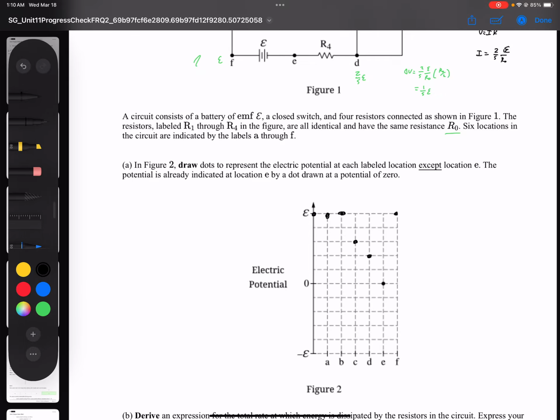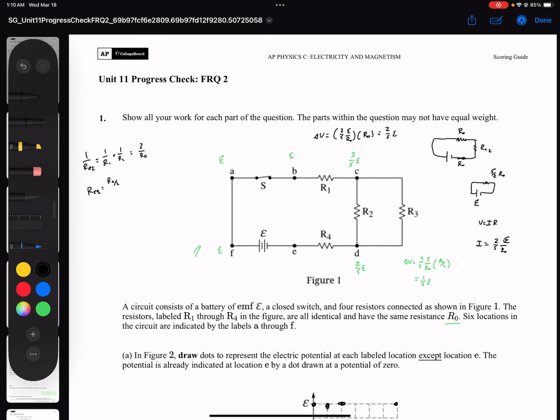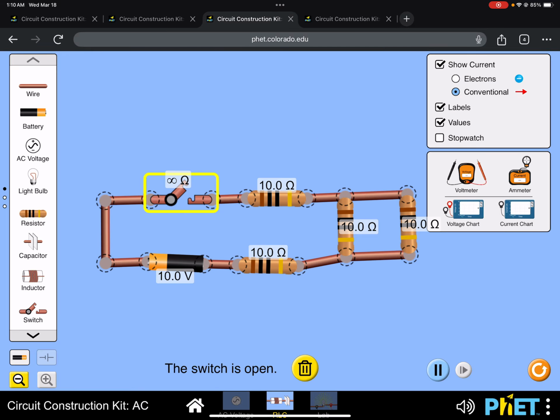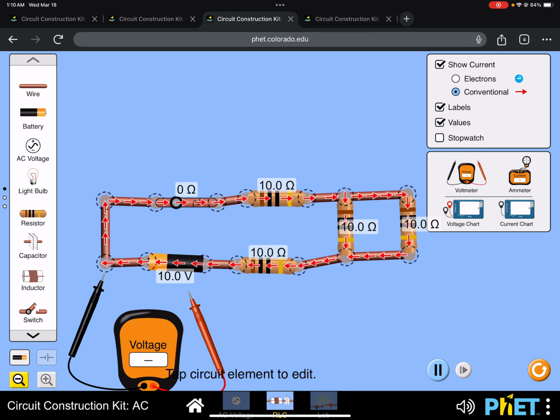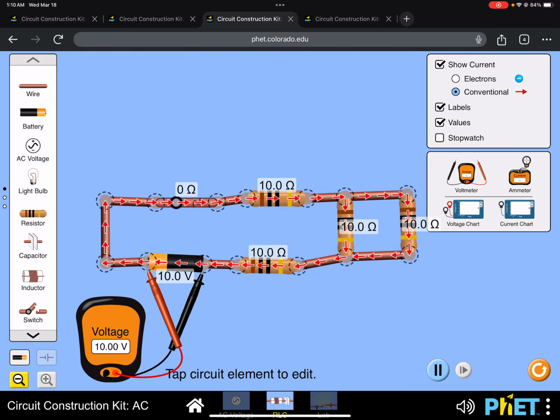So now I also have an example. Again, this is all kind of abstract when you're dealing with pure variables. Let's use some numbers. So I built another circuit, and that's this problem here. What we're going to do is turn this circuit on. We're going to have electricity flowing through the circuit, and I'm going to measure the voltage with respect to the negative terminal of the battery. So I have my black probe of my multimeter on the negative terminal, that's 0 volts. I can see here I have a nice 10-volt battery. So the voltage reading of my voltmeter is, well, 10 volts.